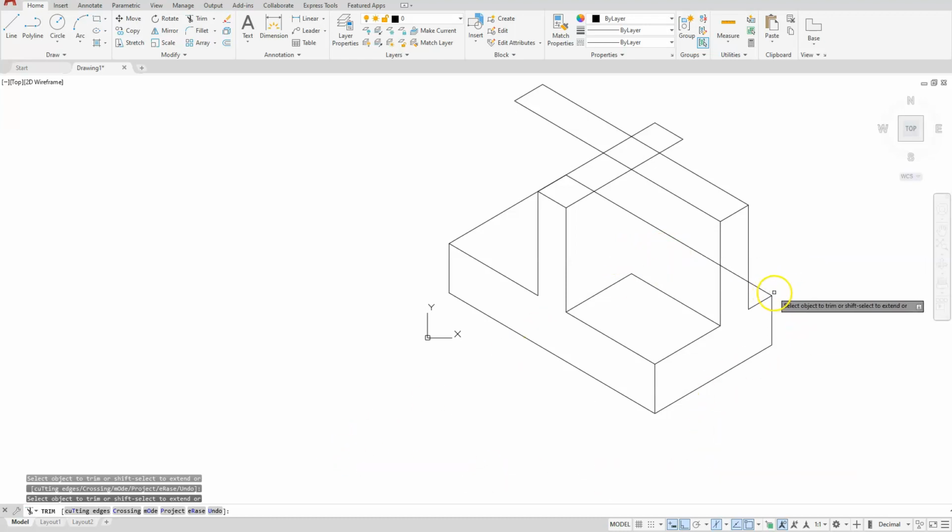I can see that this line that's going all the way back only shows up at this location. So starting at the furthest point back here, I'll click these lines forward to this location. And then here along the top, I have kind of 4 lines going across each other. So I'll go ahead and trim off the middle part.